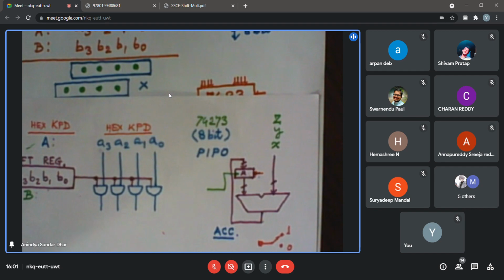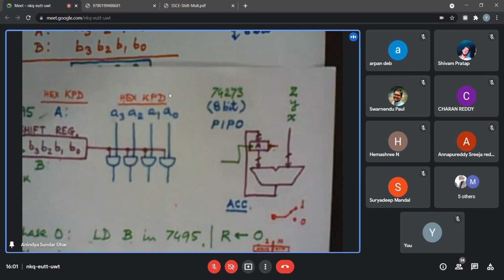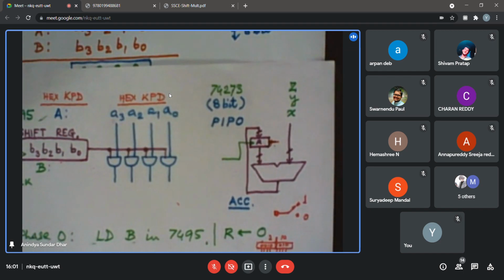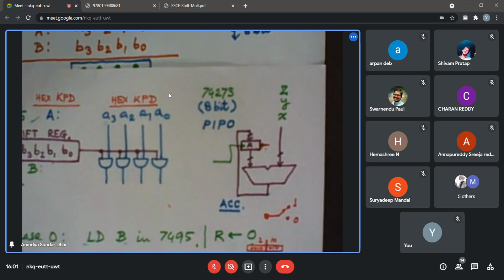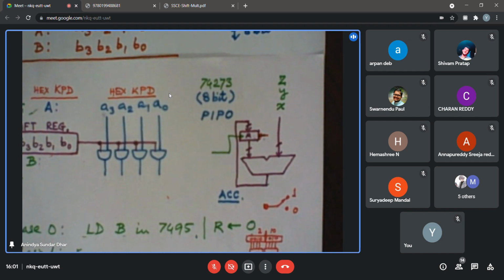So to reduce, basically we use the clock and then the staircase button will go stepwise. Stepwise means if you click on that button and you have chosen cycles as your unit, then one click advances it by one clock cycle. That means basically one edge has passed in between. Q will be fed to the shift register and Q bar will be fed to the other one. Or if you are in doubt, you can always use an inverter also. Though the inverter will have some delay, if you use cycles, that may not matter.